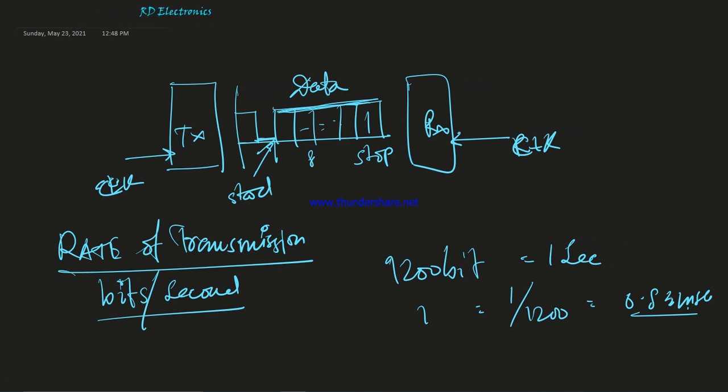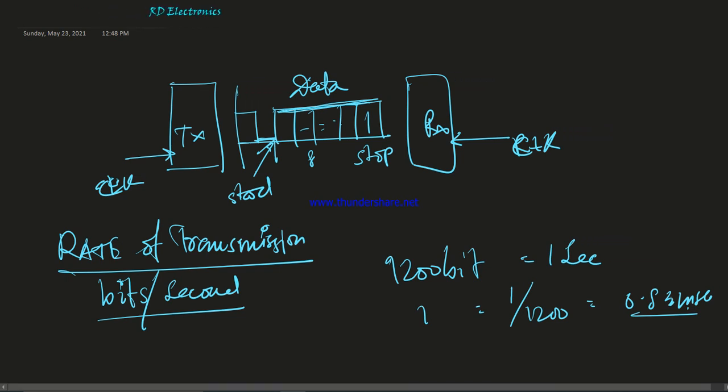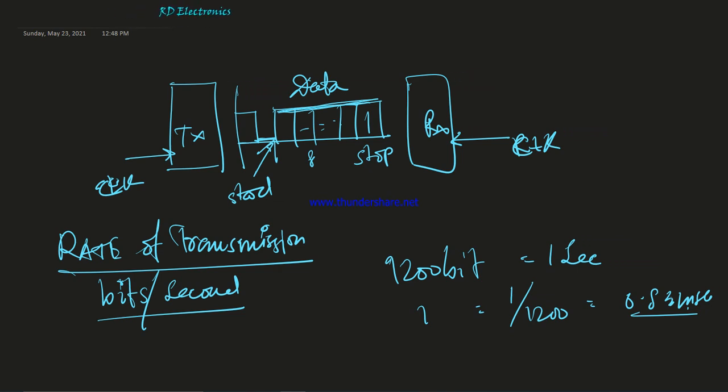Therefore, additional information for error checking is sent during transmission. The receiver can check the received data against the error check information, and if an error is detected, the receiver can request retransmission of that data segment. These methods are in common practice: parity check, checksum, and CRC, that means cyclic redundancy check.